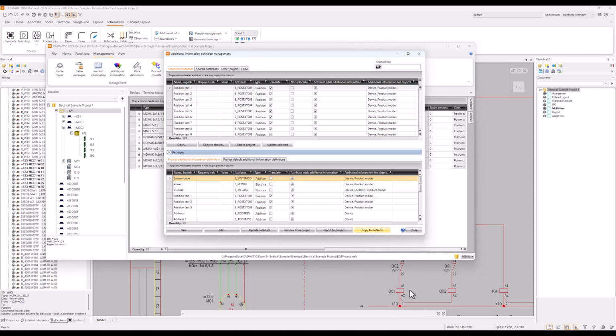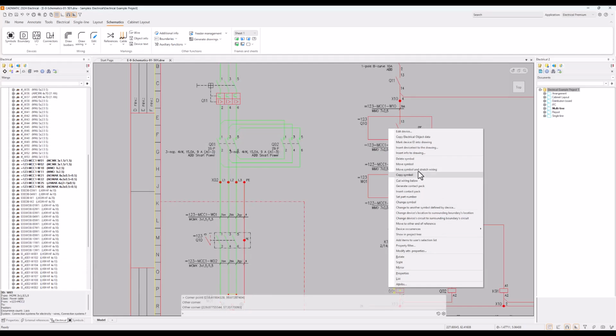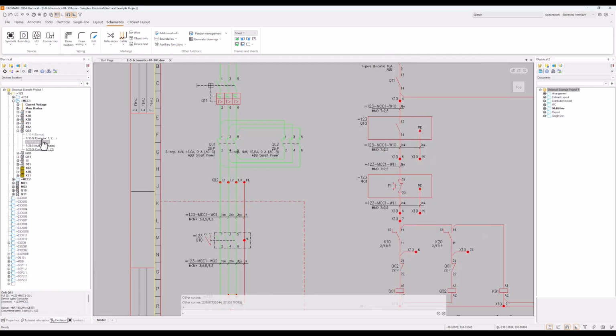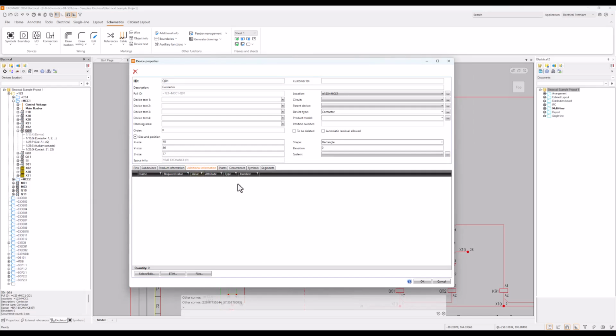These are part of this one symbol, but the symbol can have a device, such as this device here, and you can show the device on the project tree, and the device itself can, let's go to edit device, it can actually have additional information. Those attributes are only for that one symbol, but the additional information is for the whole device itself.